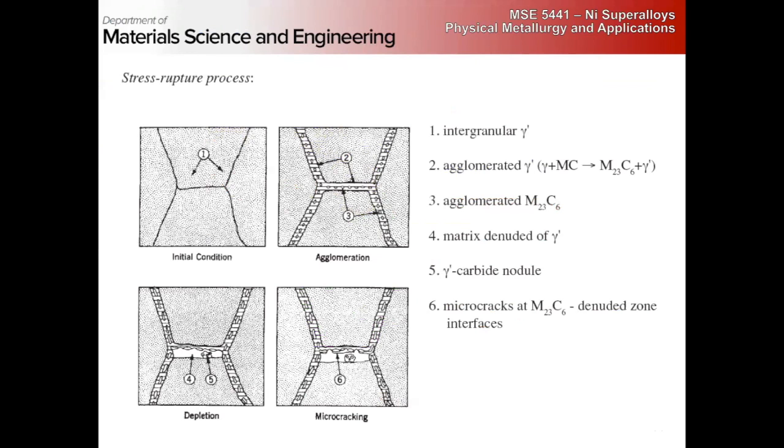As the blades expand from thermal expansion, they cut clearance into the casing and wear their own perfect fit path. After several hundred rotations, that sand is abraded away and just goes out. So the amount of strain that can be accommodated in these disks before they start rubbing is limited. You don't want things hitting other parts of the engine while they're spinning.